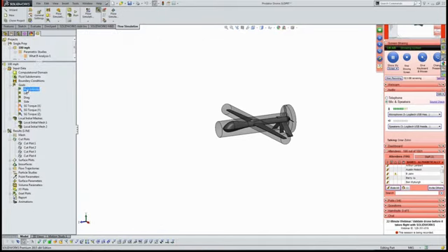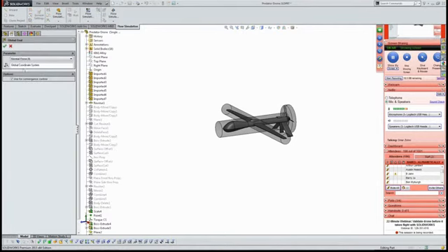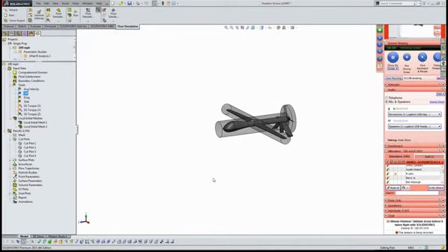The other thing is I set up some goals. For instance, I set up a goal for drag. That drag goal is just summing all of the normal forces on the solids in the y direction, and I'm using that for convergence. Anything I'm really interested in, whether it's drag, temperatures on components, average velocities, or lift, I can create goals, I can create equation goals, and then I can ensure that I've got a converged result.